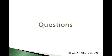How do you choose between modulators? Well, here's a question to ask. How do I choose between the modulator, input 1 or 2, if I have 2 modulated inputs in there? Well, the answer to that question is all of the modulated signals, you won't have a choice to necessarily select between 1 and 2, because once we switch from the cable TV signal to the modulated signal, all of those video signals will be distributed to the television's tuner. The A and B, the mod 1 and 2, are just options for you to expand the modulation inputs so you can have more devices.